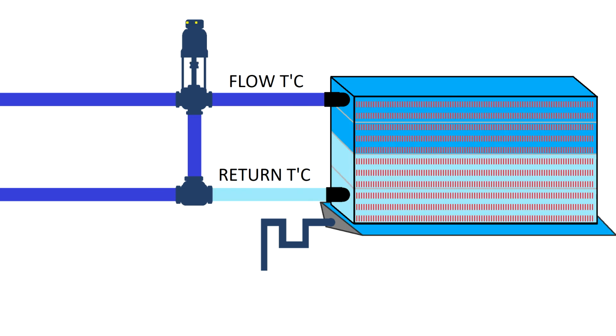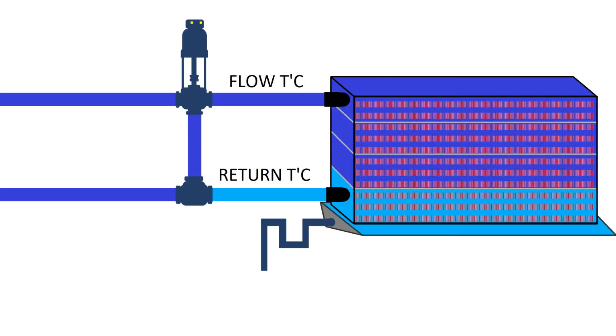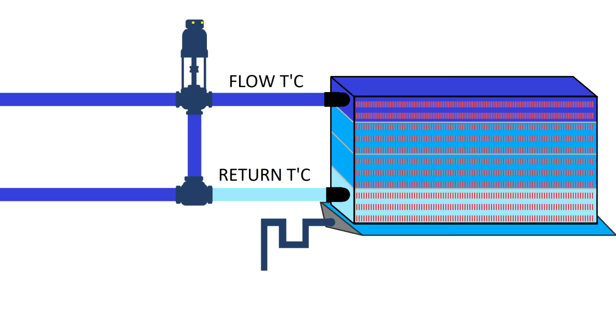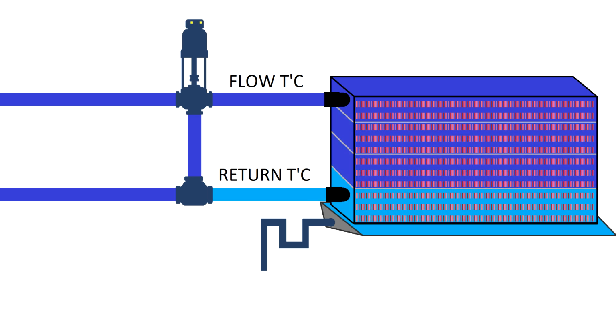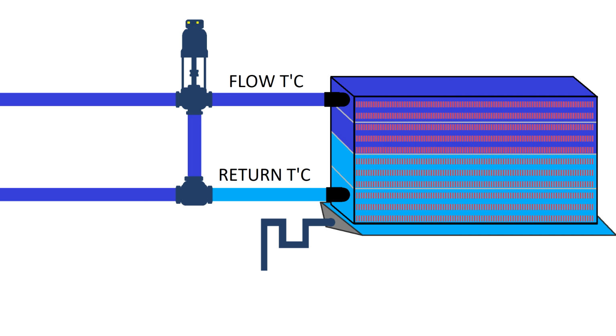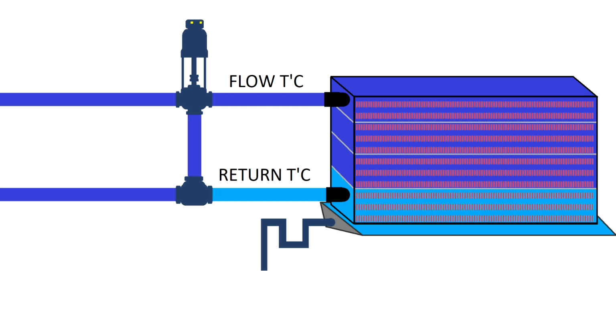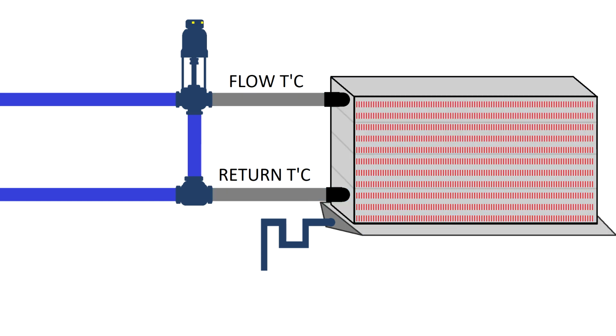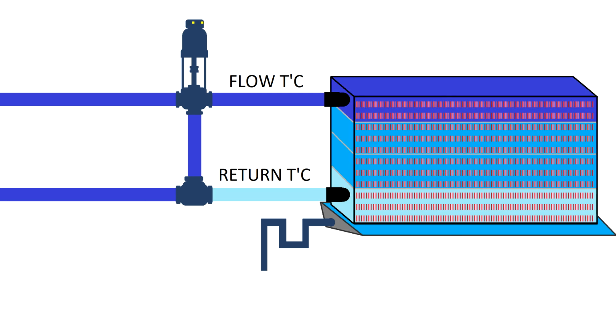If you have a problem with the cooling agent, if you don't know the cooling agent temperature, you will always focus on the actuator, PLC and the program, because you will think your programmable logic control doesn't run well. But there is no way you will know if your software or control philosophy is good unless you know exactly the flow temperature and the flow itself.